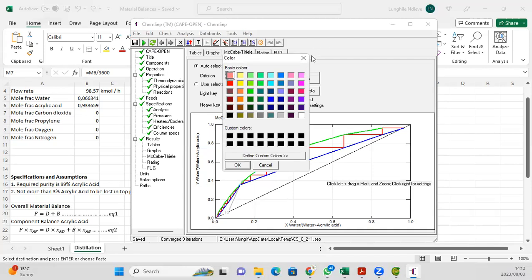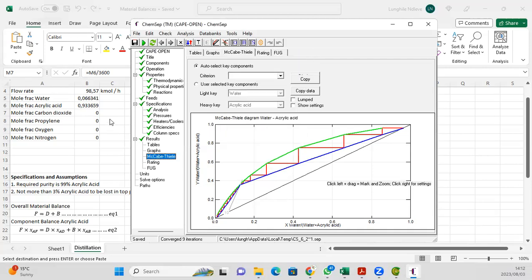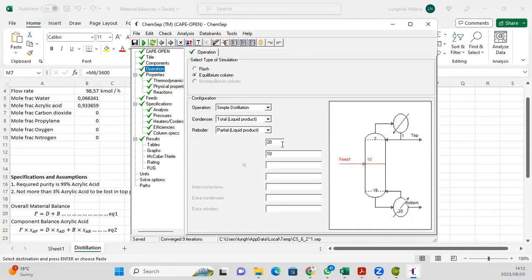And as you know, some plots count your reboiler as a stage. So we're going to use 16, because even if it says 15, 16 is still a good estimate. This is for the sake of your costing. You don't want to have more stages than you need. Your McCabe-Thiele plot allows you to use the required number of stages rather than overestimating.